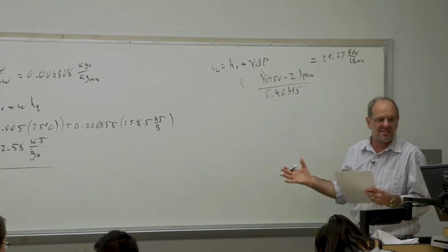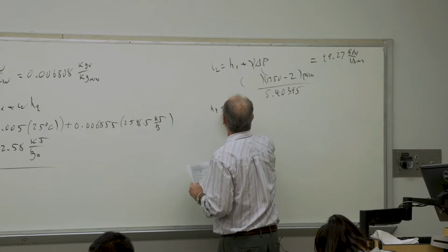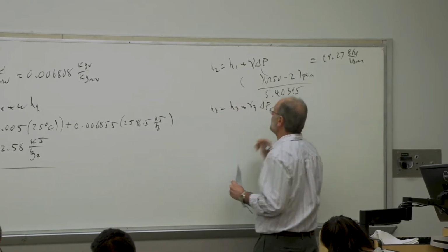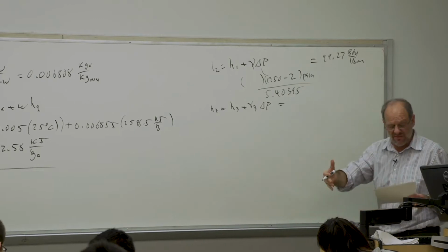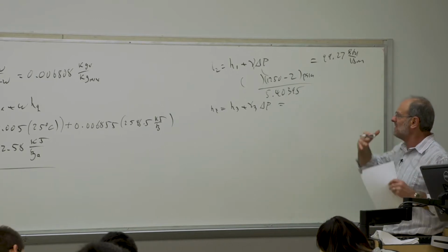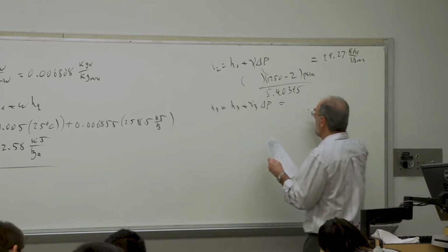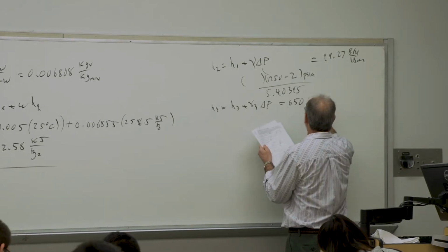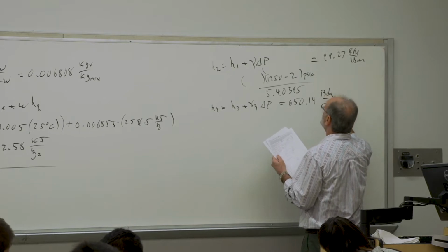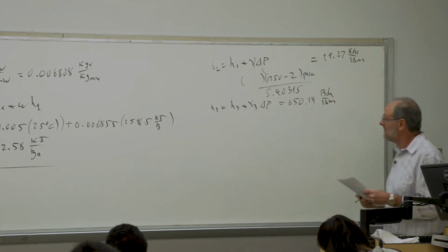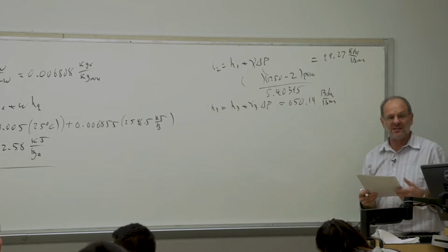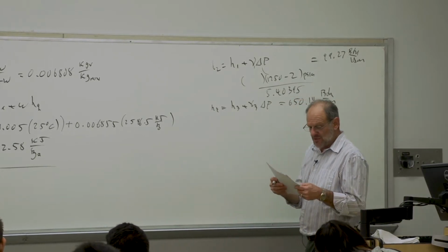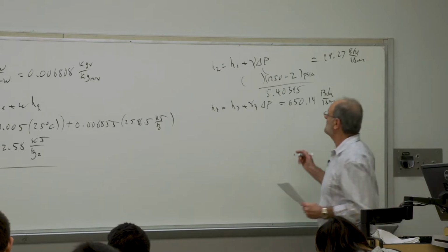And then we're going to do exactly the same thing as we find the enthalpy at 4. So this is H3 plus V3 delta P. Here we're going from 1750 up to 3500. We have to use the appropriate conversion factor. Nonetheless, we end up here with H4 of 650.14 BTUs per pound mass. So we now have H1, 2, 3, and 4. H5 is given. So now let's go from 5 to 6.